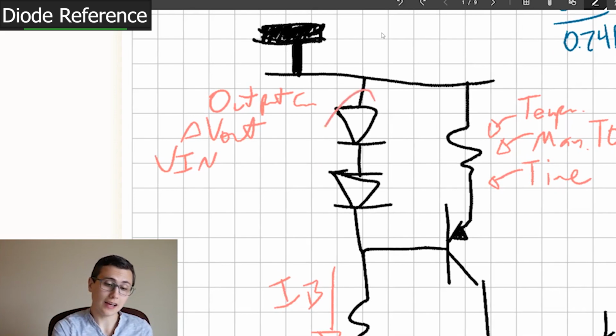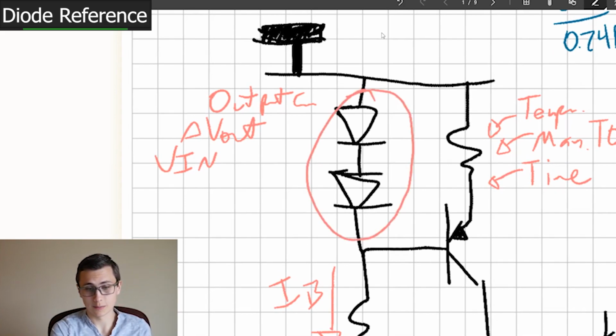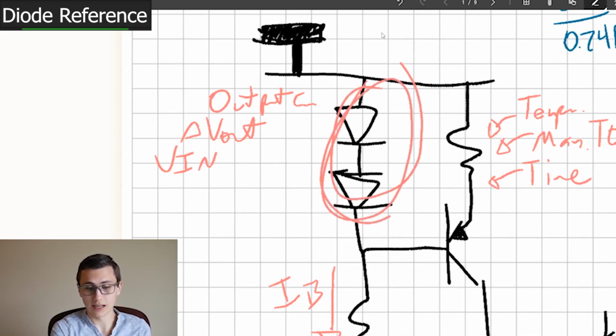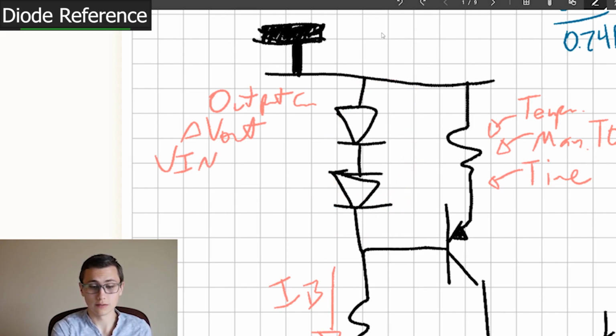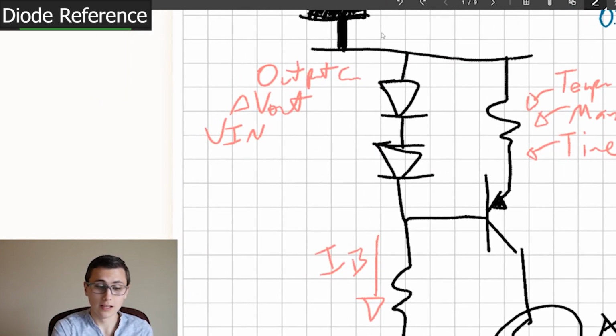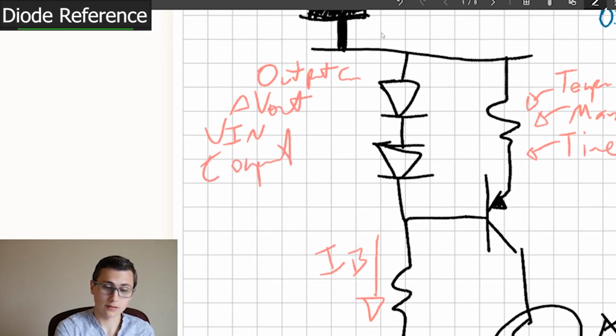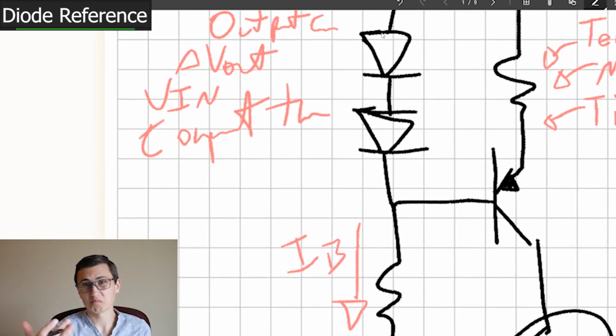There's a lot of nuanced interdependency in using diodes, a certainly non-ideal voltage reference, as a voltage reference. Not to mention we still have component tolerance on the forward voltage. It's fairly consistent, but it's not going to be spot on. Those are always typical characteristic curves. And if you look at the min-max, that can swing a fair bit.